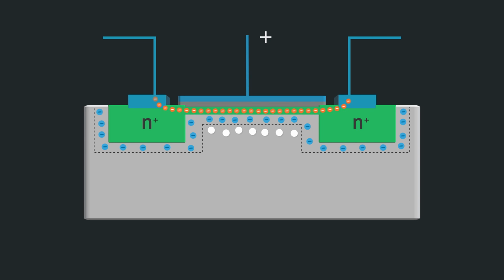This is how, using a metal oxide semiconductor structure, you can use the field effect of a gate voltage to create a semiconductor switch. And to get a PMOS device, you have an N-type substrate and heavily p-doped wells for your source and drain. And the current carriers are holes instead of electrons.